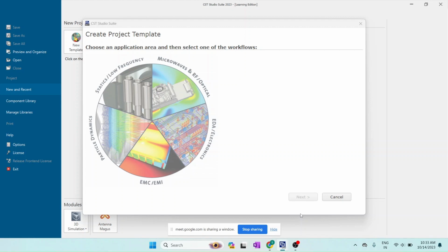What problem are we going to have? The ground plane, ideally speaking, should be at zero potential. Number 1, I assume that one of the designs is correct, where the ground is at zero potential. The remaining may or may not be. If they have the same ground plane, then everywhere you will find zero potential. But if you have given an isolated or independent ground plane to each device or each component on the board, then what will happen? There may be a voltage difference.